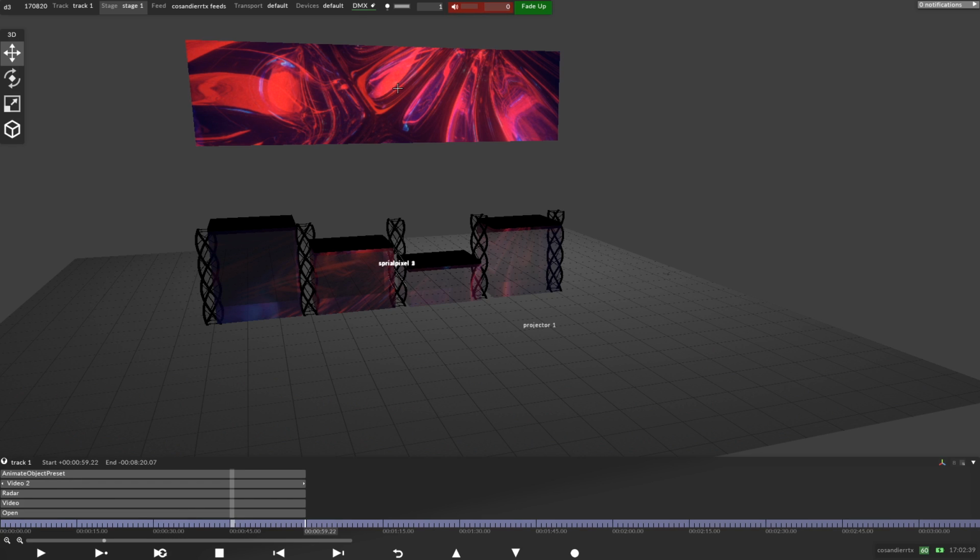Right. I brought in this, what that's going to do is 0 is going to be frame 0, 1 is going to be set through frame 359, and it will tween based on the time in my timeline between those two fixed states. So that's why you want to be able to create loops, so you want to be able to create end-to-end sections that have loopable moments so that you can transition from one look to another look if you're doing multiple types of orientations or whatever in your alembic export.